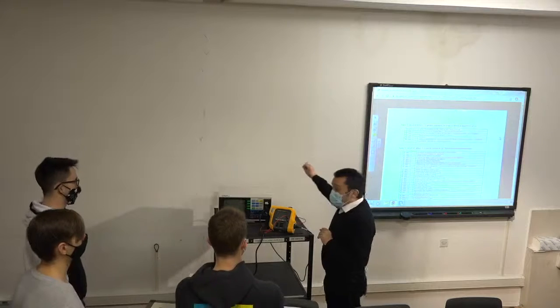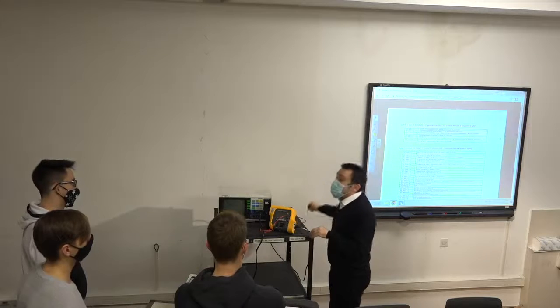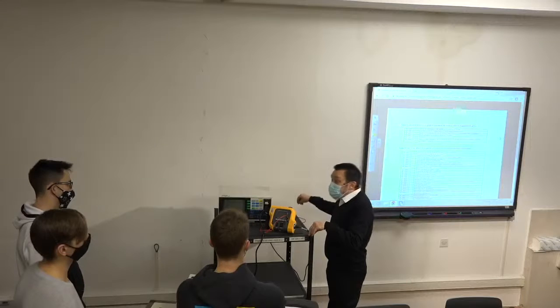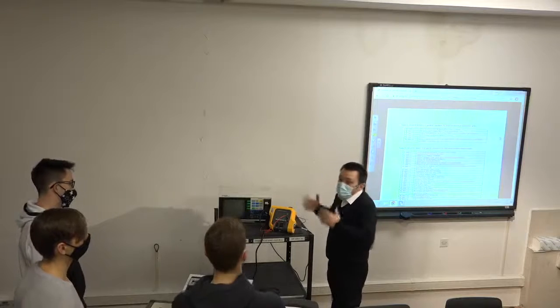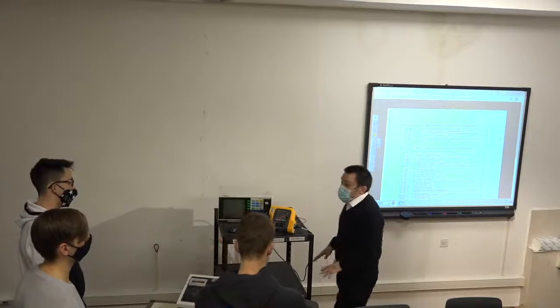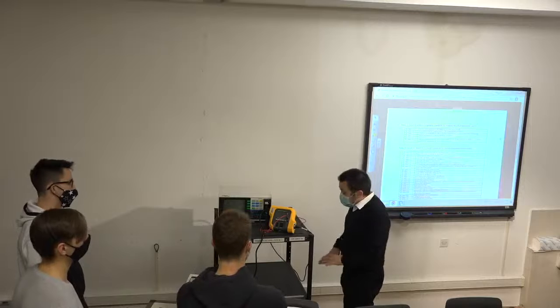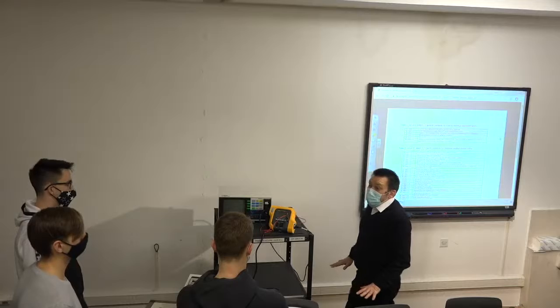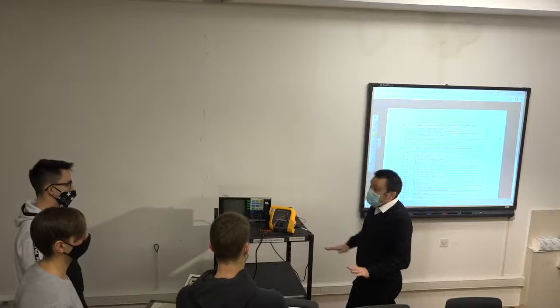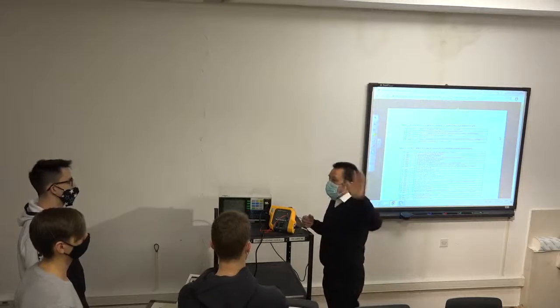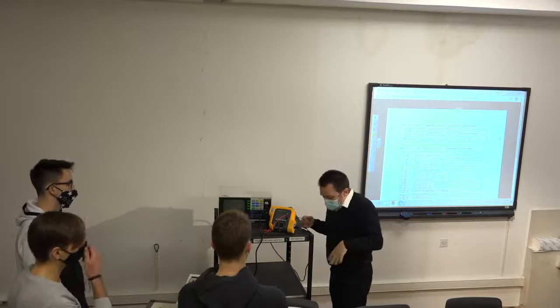So ground makes sure that you have real zero at the place where your building is, practically just beneath. This protective ground is a metal network below this building, and it has good contact with earth where it's not dry, where it is wet, so that you have at all times a very, very low resistance. What's there in the transformer, you never know.